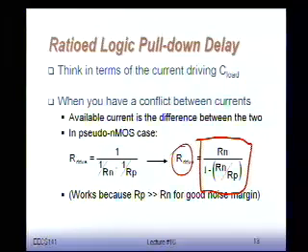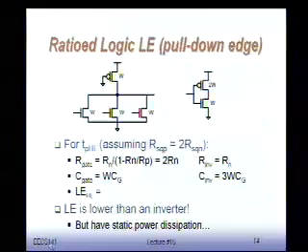So, bottom line is, both of them are right, but you have to be very careful on which one you're using, because the results can be very, very different. So let's assume that we take this one here for the time being. We're going to look at the output transition between the 50% point between 0 and VDD. So we want to look at the logical effort in that case.